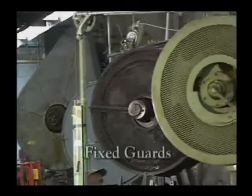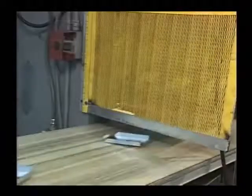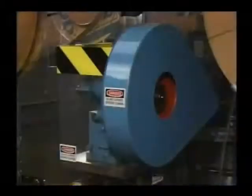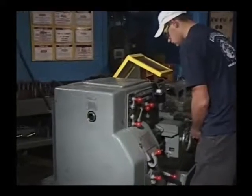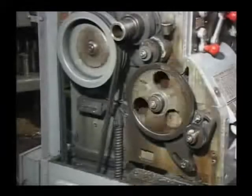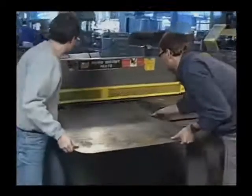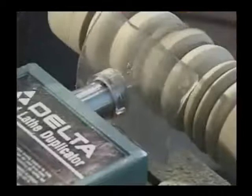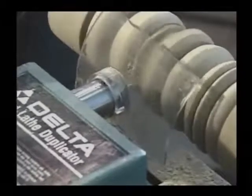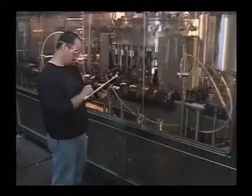Fixed guards are the oldest and simplest type of machine guard. They include things like wire cages, clear plastic shields, or metal covers which create permanent protective barriers. Drivetrains are almost always protected by fixed guards. Often the guards are built into the machine's housing in order to fully enclose the drivetrain's moving parts. Fixed guards are sometimes used around machinery perimeters and at points of operation as well. However, since fixed guards are permanent, they must be positioned where they will not interfere with the worker's ability to access or operate the machinery.